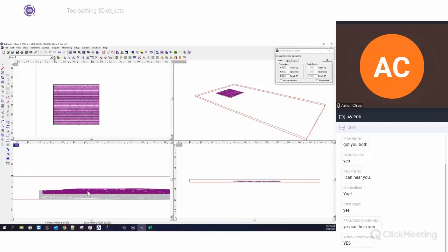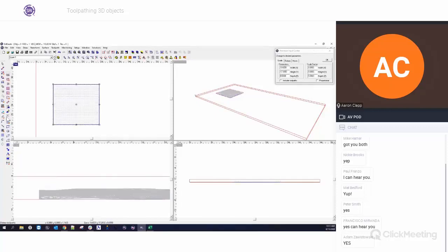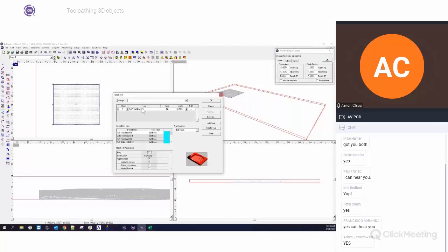We're going to grab this and delete the toolpath. In this case, we're going to go back and set this to 1 inch. That's going to be the setting that we want to use for this. Now, hatch, as you guys know, hatch fills and island fills automatically offset 1/2 the diameter of the bit in order to account for the edge of the material.